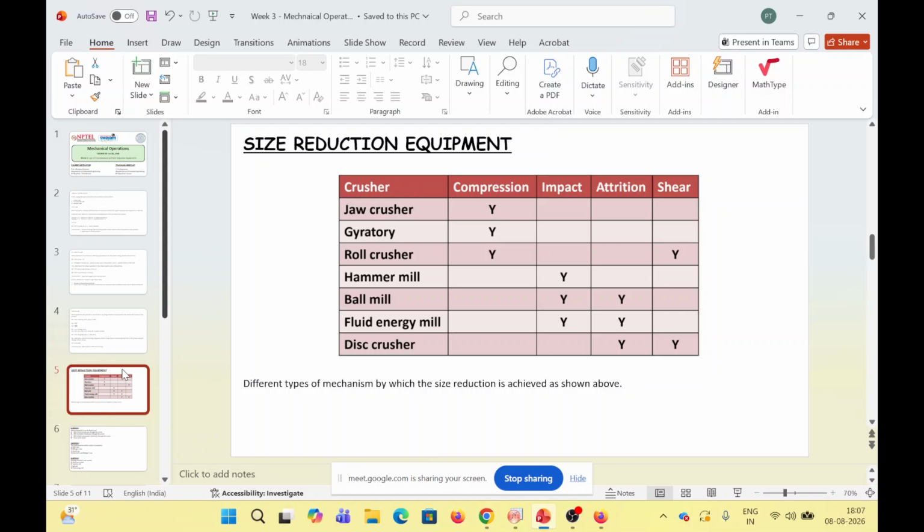Based on the speed of rotation, there are two types of forces responsible for breaking the particles: impact and shear force. When you start rotating the cylinder until it reaches a particular speed, it is the shear force which is predominant.